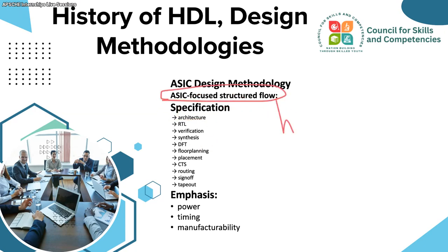It is high cost, because it is for only a specific design, application specific. It is for only one application, not for general purpose. So they have their architecture and RTL verification, synthesis, the design for test flow, floor planning, placement, and then CTS, routing, sign off, and tape out.